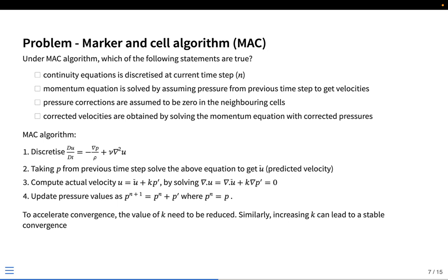So if you see the flow of how this algorithm works, you start with your momentum equation first. We already assume a given velocity and pressure profile, and then with the assumed profile, you integrate one time step. So from the current time step at t equal to 0, initial conditions have to be provided. So from the initial condition, you move one step ahead, and once you are done one step ahead with the assumed pressure, obviously whatever velocities you're going to get are not the correct velocities, because while solving for the momentum equation, we have not accounted for the fact that the velocity has to satisfy the continuity equation. Now we have to somehow incorporate that information into this. So the first step is you get an intermediate velocity, which let's say we call the predicted velocity. So we have to correct the predicted velocity.